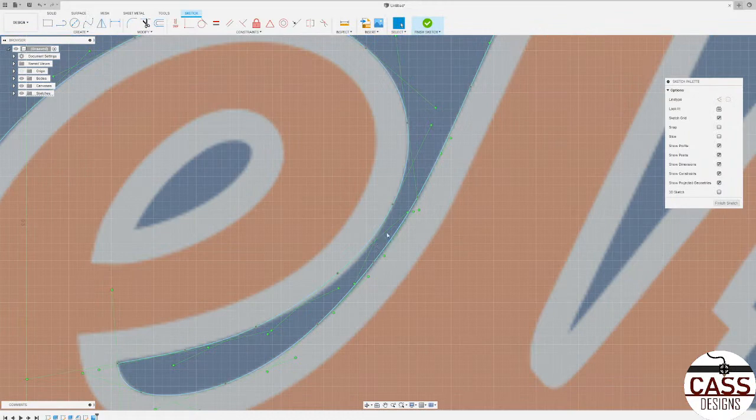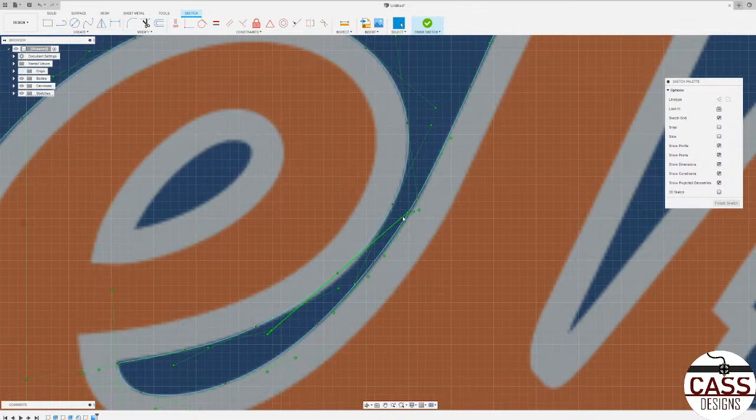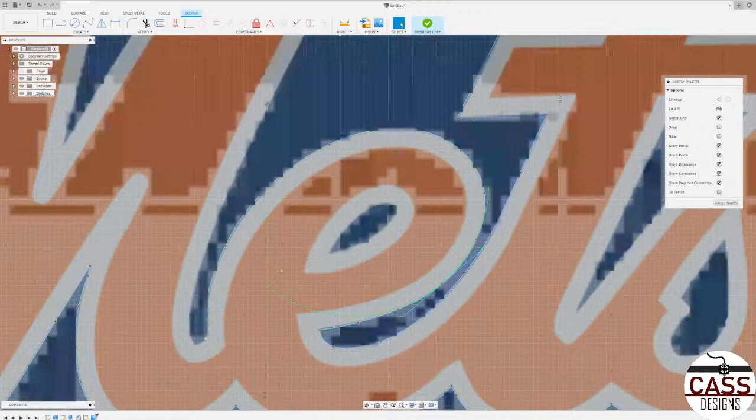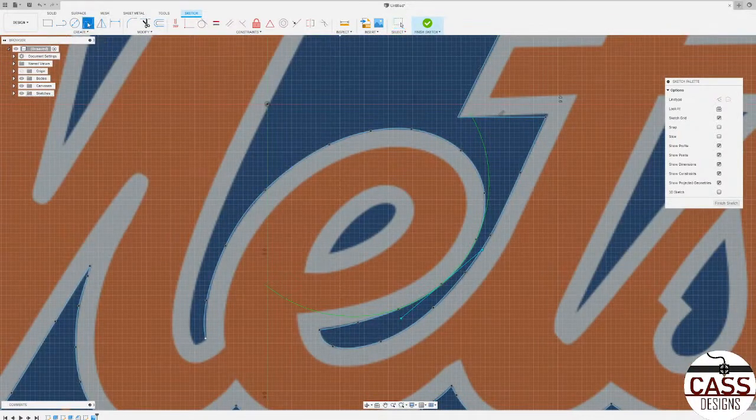You can see there are these green lines here. What you can do is drag these and move them to fix the curvature of it. You can move this around, which will help us fix it. If you grab the end of it, it changes the rotation, so it screws up the whole spline, so I don't really want to do that. So I'm going to leave this here, and that's looking good. All right. So that's another thing that you can do with splines.